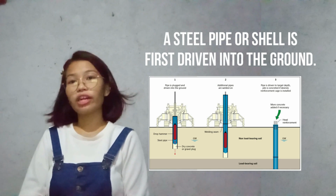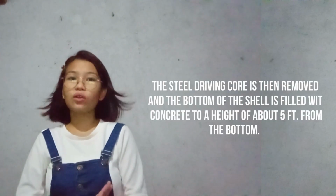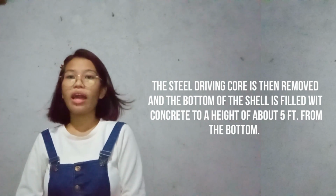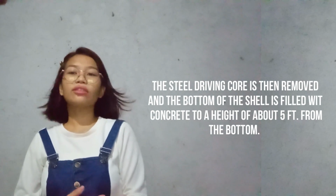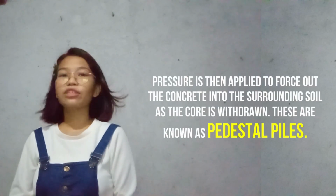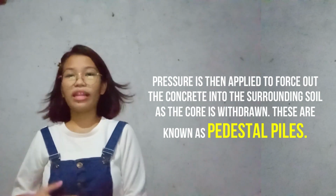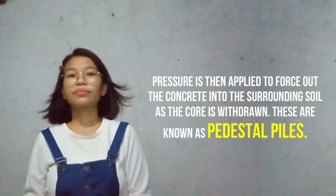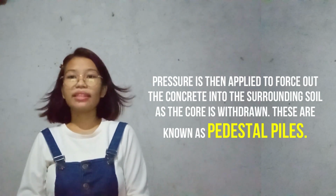A steel pipe or shell is first driven into the ground. The driven core is then removed and the bottom of the shell filled with concrete to a height of about 5 feet from the bottom. Pressure is applied to force out the concrete into the surrounding soil as the core is withdrawn, and these are known as pedestal piles.